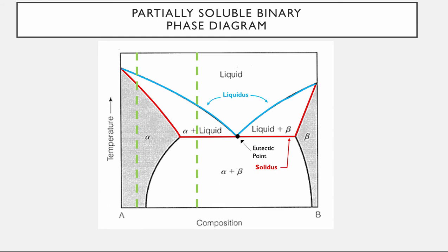Instead, if we had too much of material B and we were over the solubility limit, then as the material cools and we get below the solidus, then we just have solid A and solid B interchangeably held together, just like we learned in the insoluble phase diagram behavior.